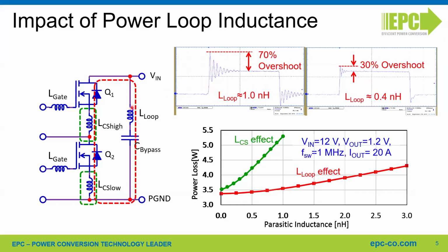So this is bouncing energy between the output capacitance of the device, the parasitic inductance of the power loop, and this is causing additional currents that are causing losses. This is one factor. The other factor is you can have higher power dissipation in the overlap interval of the switching edge because of the higher voltage that is reached by the device.